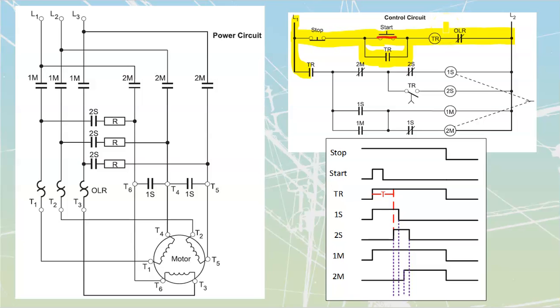Once again, timing relays can have multiple different types of contacts that come off. Some are timed, some are instantaneous. As soon as it seals itself in over there, it is also going to seal this in over here, which is then going to apply power through those which are closed out to 1S. Power is going to wait over here.